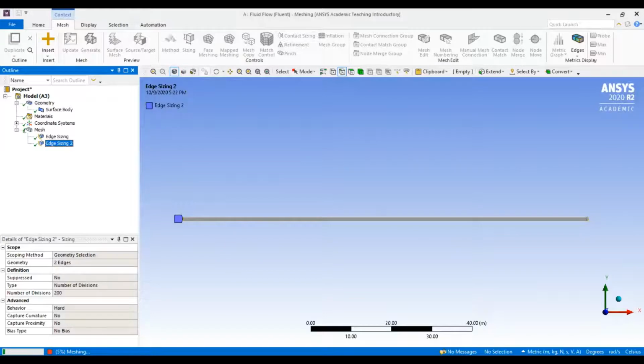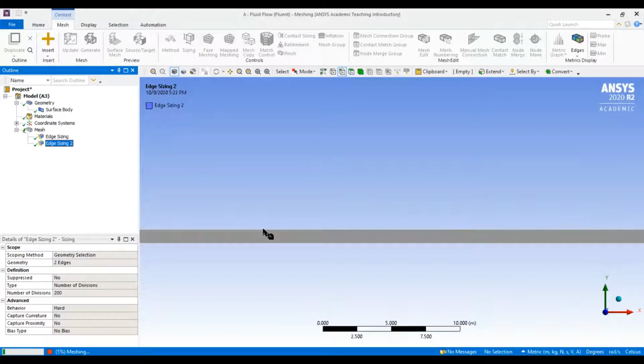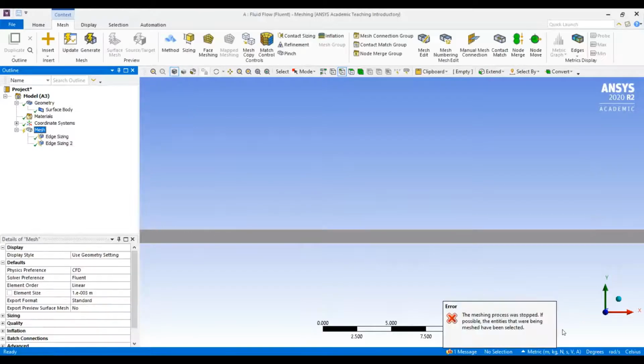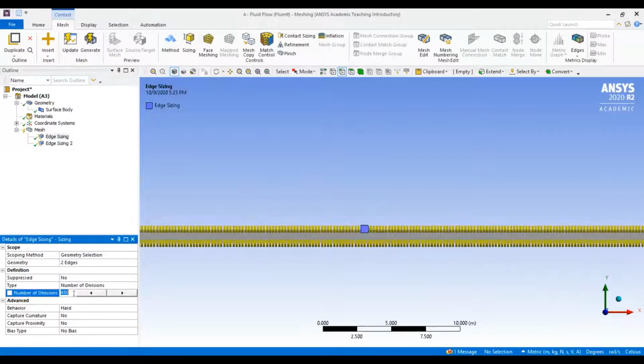This is not going to be the final version of the mesh. What I wanted to show is that the mesh would not have been correct. It would have been rough and all over the place. And I just wanted to demonstrate how it would have looked. So I'm just going to stop it early again to do the final step early, so that hopefully the mesh works. Actually, I'm going to pull the number of divisions down to 400 here. I think it should be okay. And I just want to make sure that the meshing actually happens.